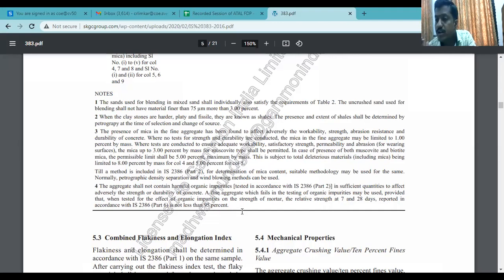ह्या सर्व गोष्टी जर तुम्ही रिव्हर सँड आणि क्रश सँड कम्पेअर करायला गेलात, एम सँड, द एम सँड दॅट इज मॅन्युफॅक्चर्ड सँड, एम सँड म्हटलं जातं मार्केटमध्ये त्याला, किंवा आर्टिफिशियल सँड तुम्ही असं म्हणा त्याला. तर ह्या सँड आणि रिव्हर सँडच्या फिजिकल प्रॉपर्टीज सेमच आहेत. त्याची स्पेसिफिक ग्रॅव्हिटी म्हणा, it lies in the range of 2.5 to 2.70. Okay, again crush sand, the same range we are having for the M sand. Water absorption should not be more than 2% at any cost.